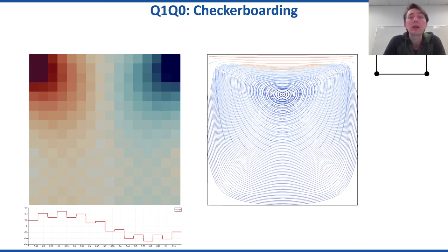Now, just like in a previous example, we saw that this result is highly dependent on our computational geometry. I assumed a simple square, and for the mesh, I assumed a uniform distribution. But for different geometries and different element distributions, you would get other pressure modes that might not be as straightforward to show and to compute, but they would be there, and they would also spoil the result. So these are now two different elements that we're able to show just by counterexamples that we're not going to get good computational results.